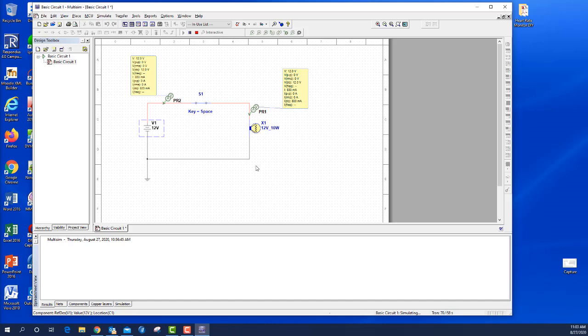So yeah, it's 833 milliamps. Actually 833.33333. So if I use the Ohm's law formula for calculating what the current would be, it's exactly what we're measuring here. So that's another good thing about Multisim. If you're doing calculations and you want to confirm whether your calculations are correct, Multisim can kind of help check your work.